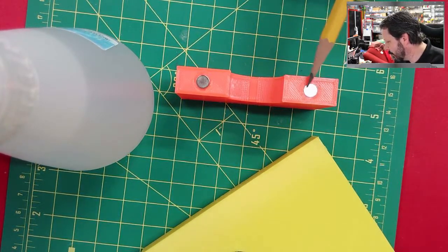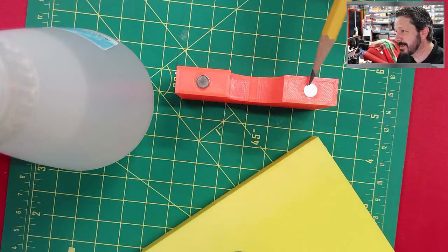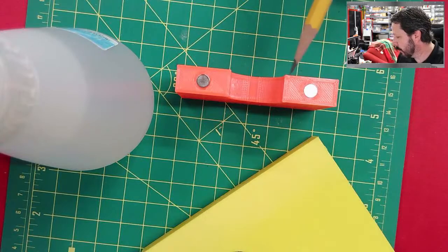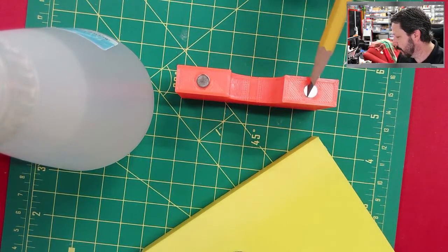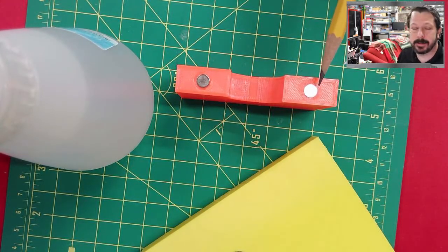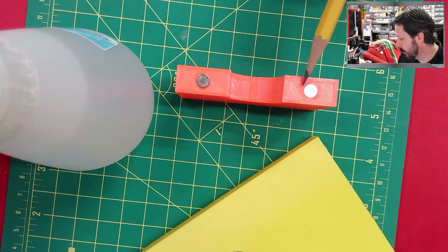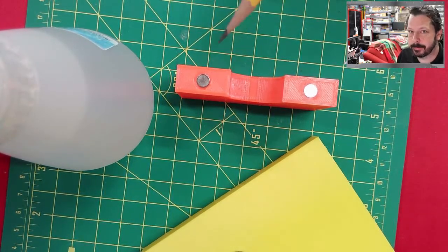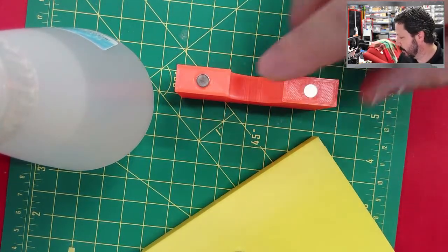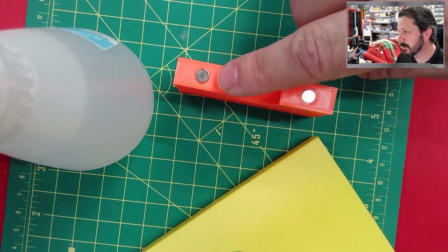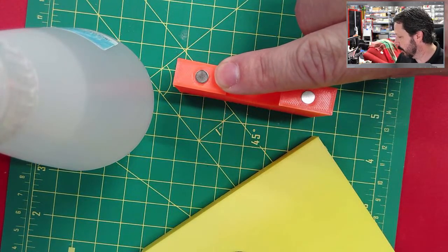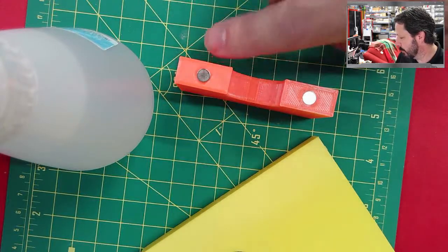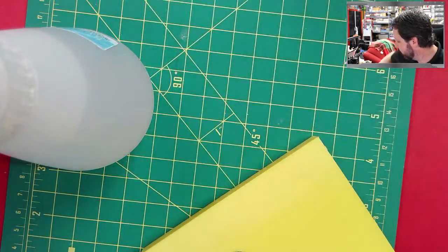But I wanted to snap these magnets inside here, so I needed some structure around them. Walls aren't only on the outside, they're also around any holes that are in the part. So I wanted some extra walls around here so that when I put these magnets in, they didn't just fall out. I wanted a little bit of resistance to pressing them in. In fact, here you can kind of tell that one broke a little bit. It broke the support underneath it, and it inset a little bit more than I wanted. But it works fine.